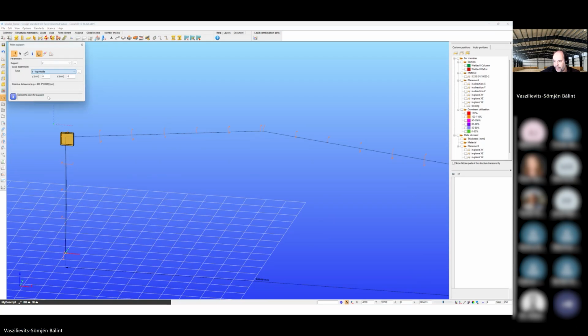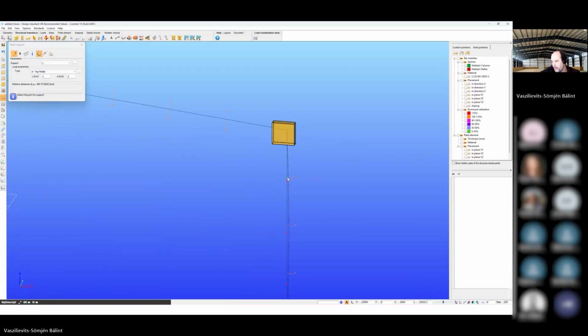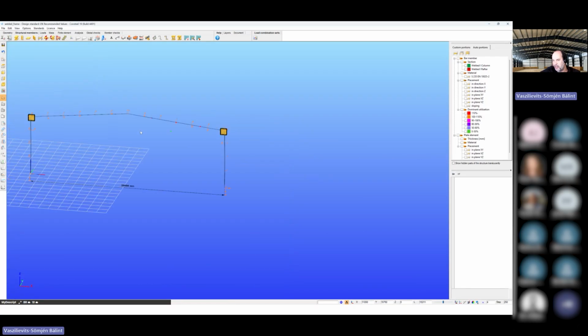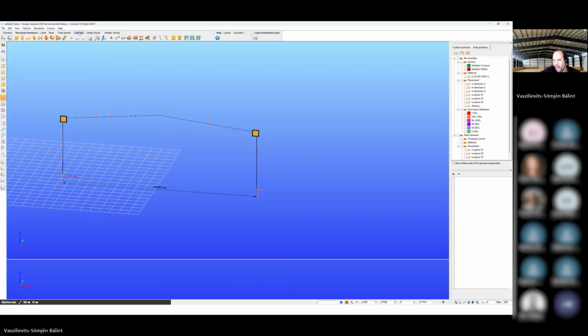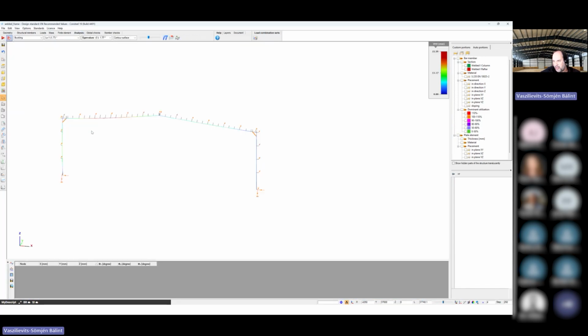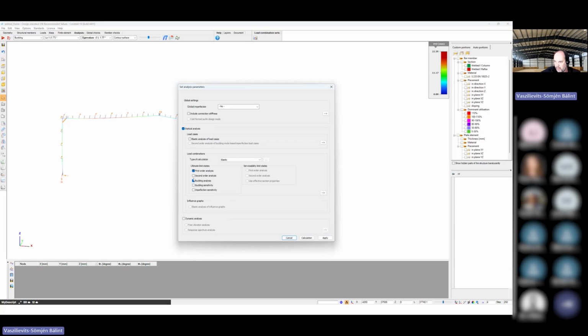column. And now I repeat the calculation. Because I want to do something more precise, I also want to activate the buckling sensitivity analysis. Buckling sensitivity analysis is that part of the feature of Consteel I don't want to speak about now, but this assigns the appropriate buckling mode shapes to the different members of the structure.